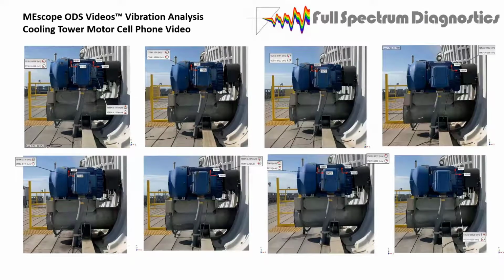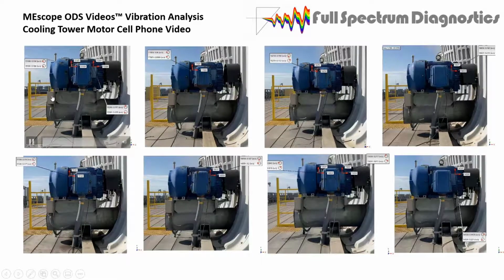This is the 8 channels of the cell phone video for the whole machine, and they'll all start shaking in a minute here, kicking in. So if you take a minute to look at these and look at the piping and support structure under the motor, there's some twisting value there, and I think it's torsional in the motor.